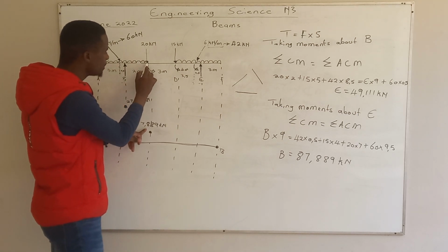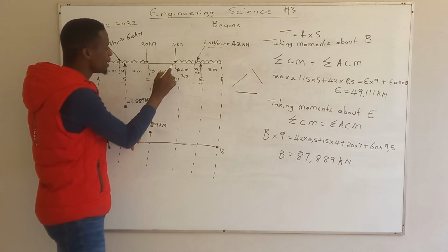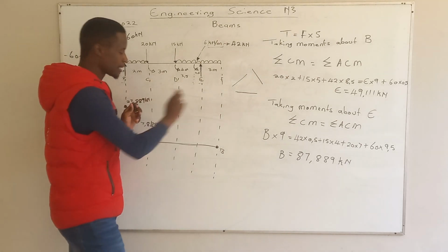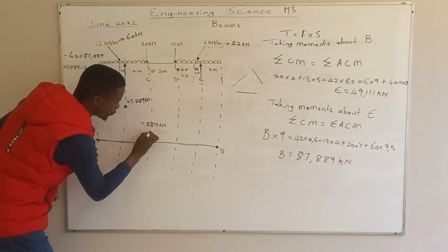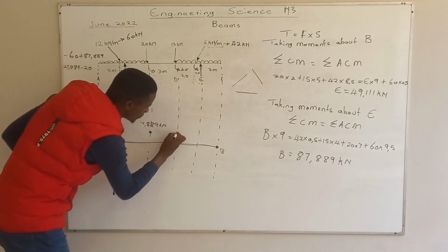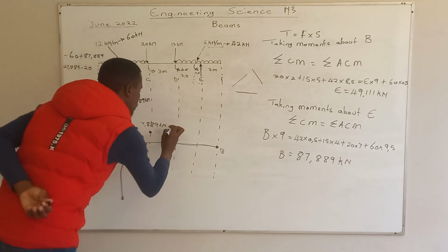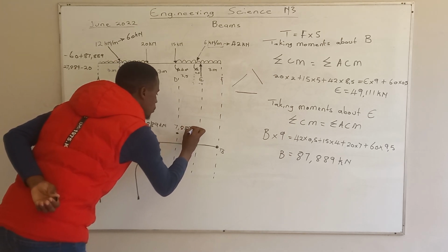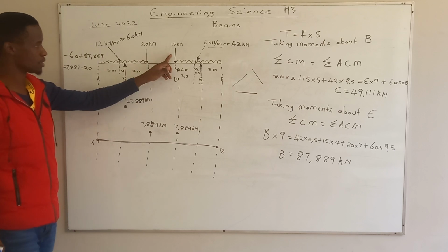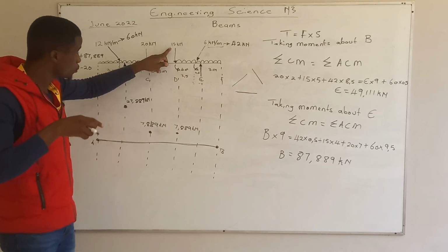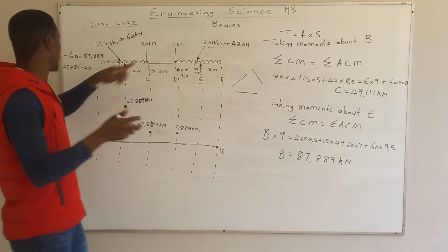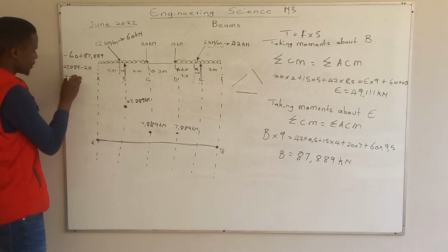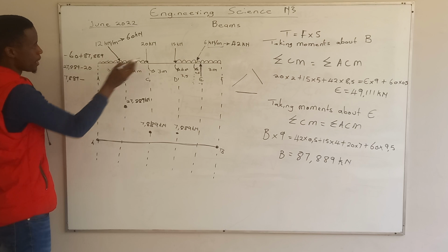Then it's from here to here now. From here to here is just the distance. Now we're going to go 3 meters wide, 3 meters to the next force. So from here to the next force, we're still having our 7.889 kilonewtons, which is this one. Now, for this one, since it's negative, it's 15, you're just going to say 7.889 subtract our 15.